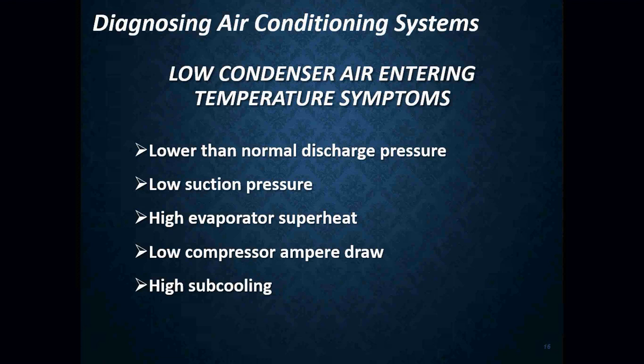Think about an air conditioner that's running in the middle of winter. Okay? It's cold outside. What's going to happen with my pressures at my condenser? They're going to be lower because I have low condenser air entering temperature. It could be 20 degrees.